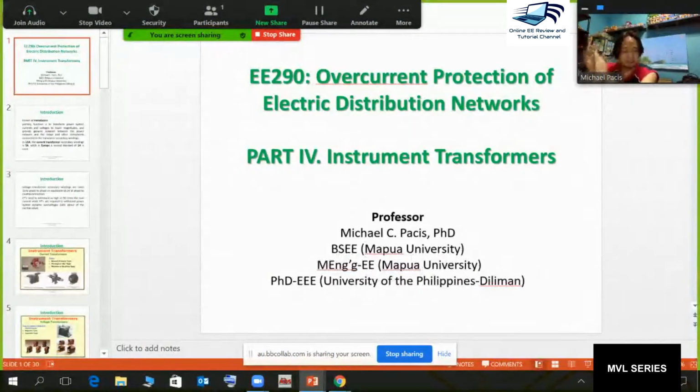If you can still recall, the relays have CTs, and every current transformer, in terms of the design, has a burden. So you need to multiply it by a certain ratio factor or the effective turns ratio so that you can get the actual CTR of your current transformer.